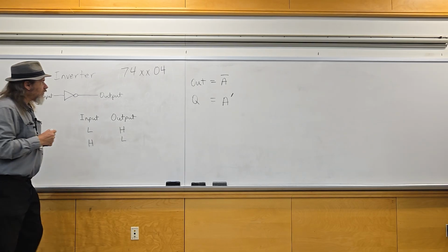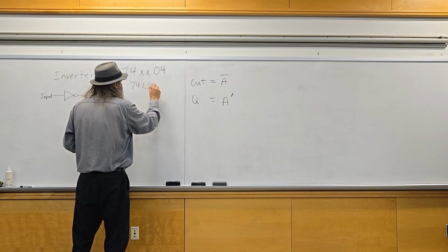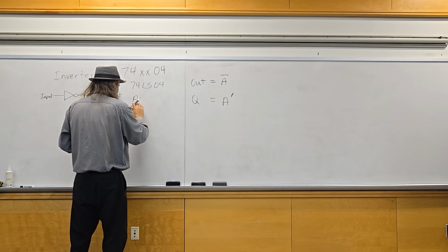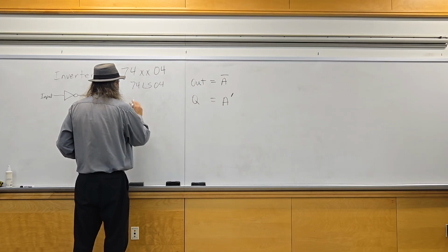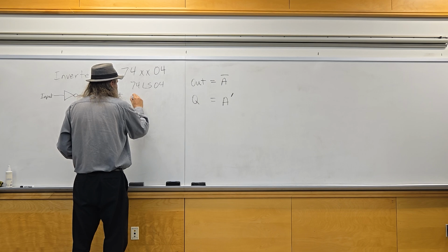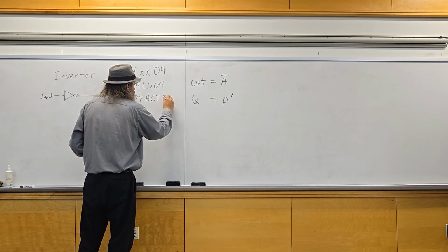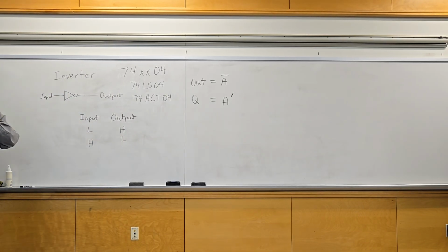So older technology might be a 74LS04. Newer technology, I believe, the more stable and clean is 74ACT04. Functionally, they're the same. They have the same pin arrangement on the chip, all that sort of thing. So no big deal there.